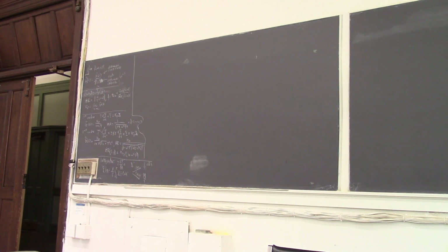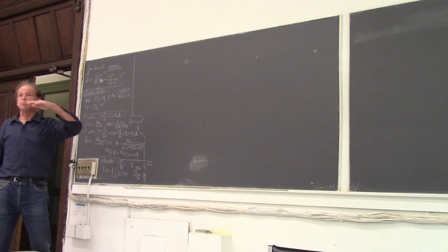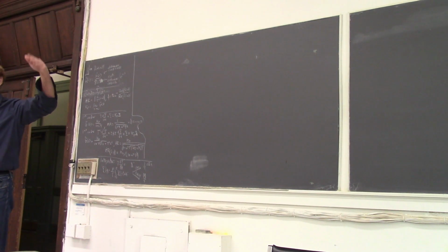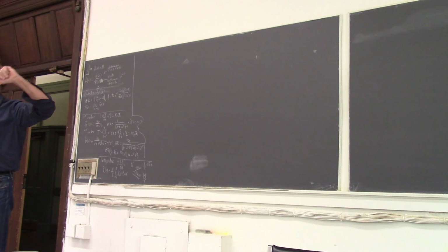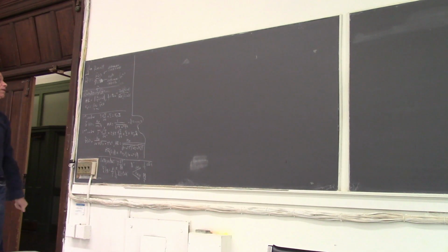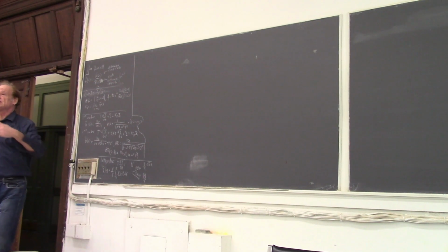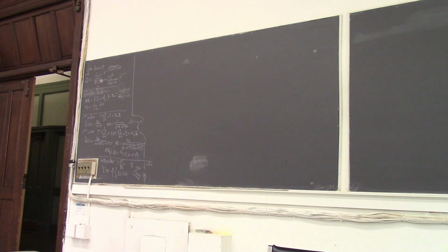So it's the roots of the denominator and not the numerator that determine stability, because the time dependence has an exponential. It may be an exponential times sines and cosines, but sines and cosines just oscillate, exponentials grow. Now, of course, you could have t to a power times an exponential times a sine and cosine as well. But generally, it's the roots of the denominator that determine whether something is going to blow up exponentially or linearly, or as a polynomial, or decay polynomially or exponentially.